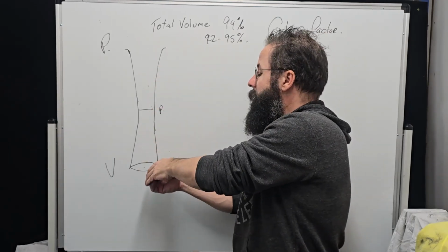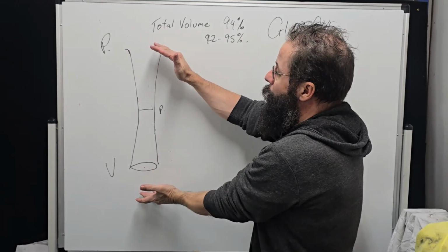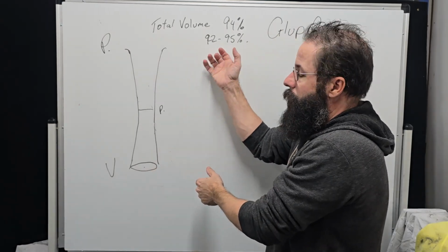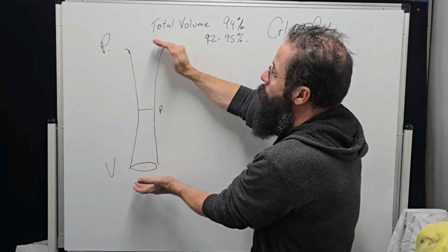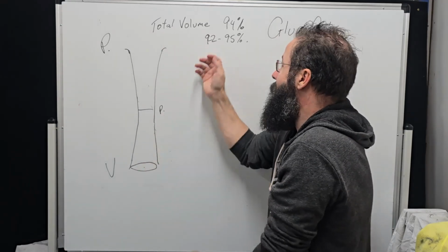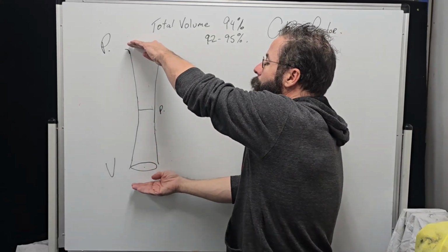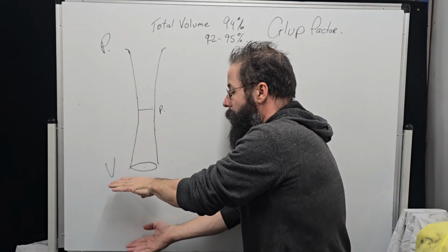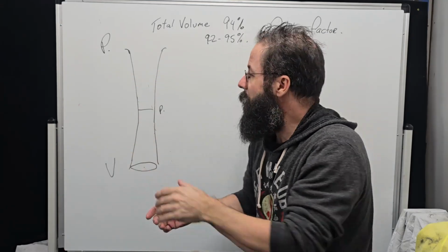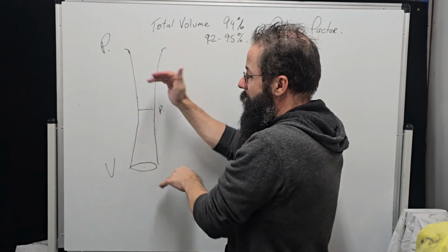So each time the piston pulls down, it's going to gulp that amount of air. And the closer we get to that 92, 95%, the better it seems to be efficiency-wise, because we're only replacing the runner pretty much. So if we just took round numbers, said 100%, then all the air is already in the chamber. So all it needs to do is replace, and then this section fills that section.